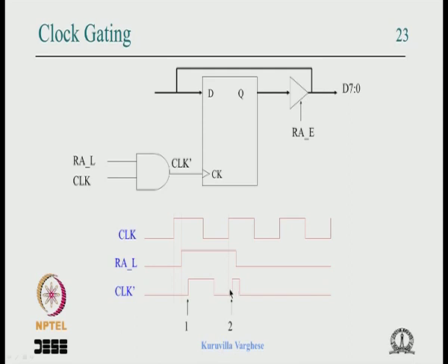the data gets latched here, but we don't know whether the data will remain there, because that register is clocked by this, and already the output is changing. Maybe this is coming in after the whole time window, and then wrong data can get latched. Suppose this is a counter which is getting incremented on this latch signal. An edge comes, it gets incremented, probably again it gets incremented and so on. So this is because of this glitch. This scheme is not timing wise very neat.